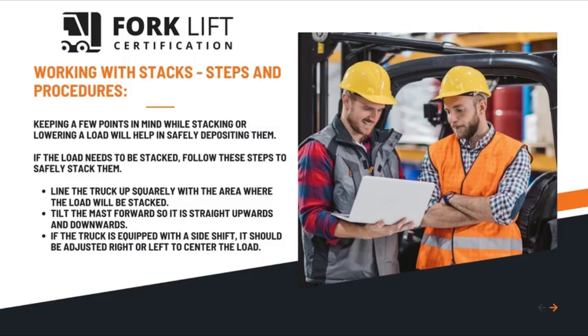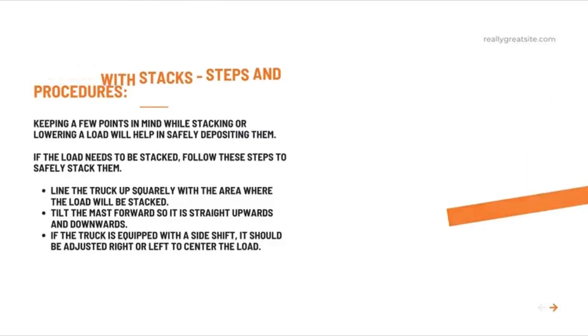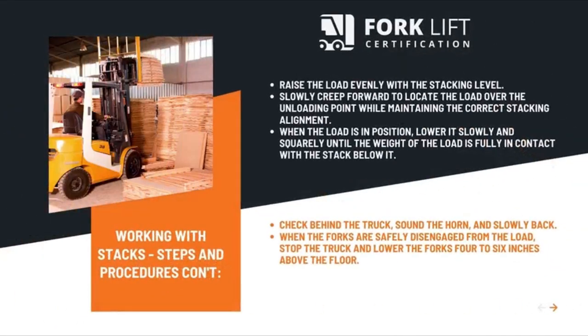If the truck is equipped with a side shift, it should be adjusted right or left to center the load. Raise the load evenly with the stacking level. Slowly creep forward to locate the load over the unloading point while maintaining the correct stacking alignment.